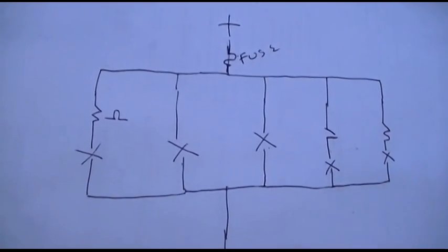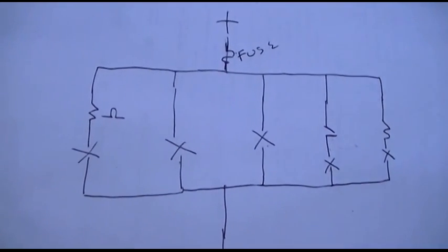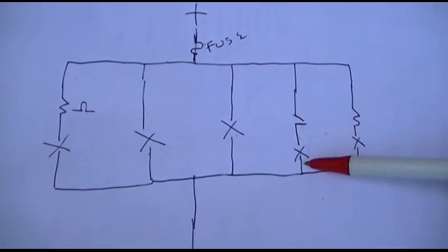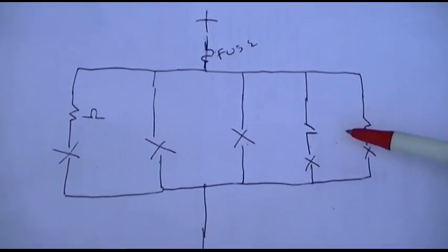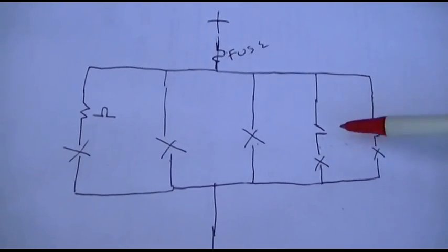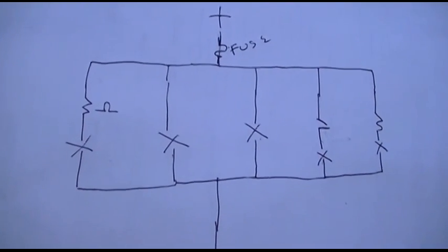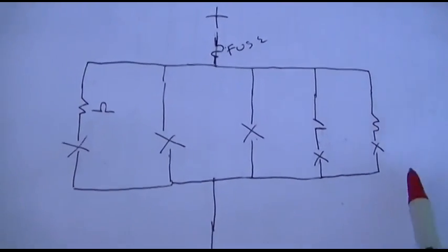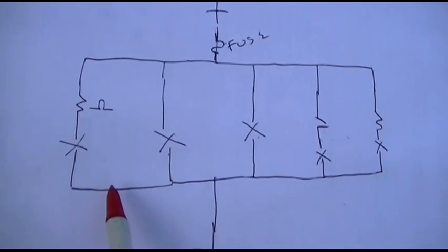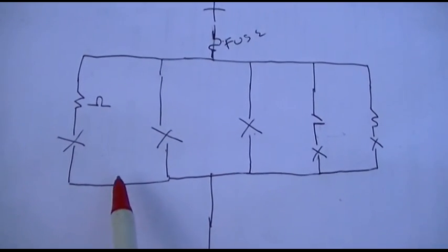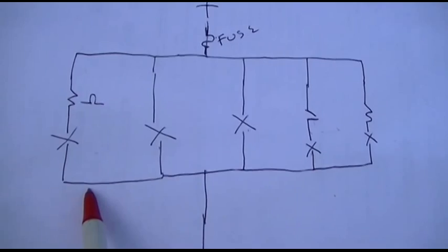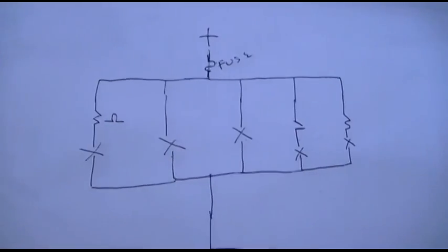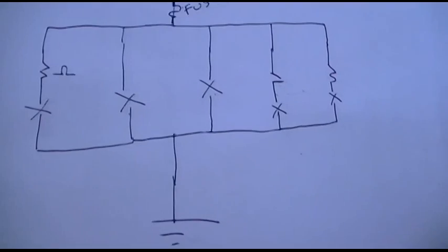You can first of all start by kind of logically ruling out certain things. For instance, the trunk light, you can check that by disconnecting the switch. The only real way to do this, in more of an automotive application or a house wiring type application, is to start disconnecting things.